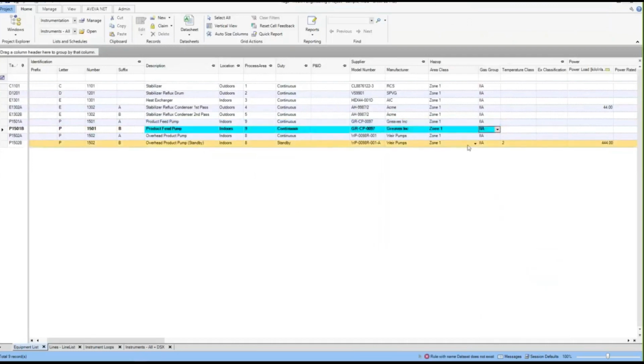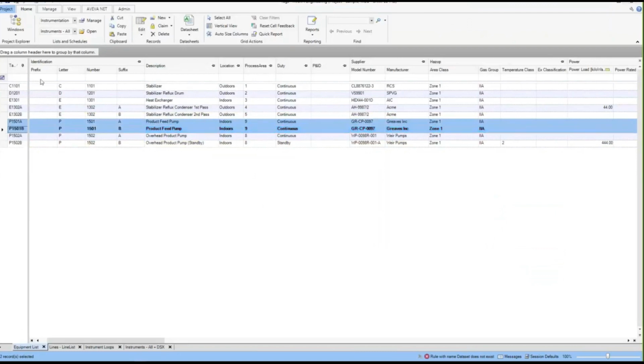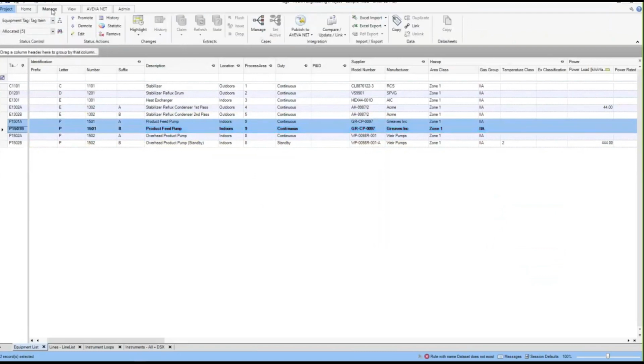The nice thing here is that we can link the two objects. In this particular case, I haven't linked them, but if I wanted to, there would be specific attributes on these two objects that are linked. If they're both main pumps, or a main pump and a standby, and you enter the design or engineering conditions, pressure, temperature, etc., that are common between the two pumps, then every time you modify the pressure, temperature, or other linked attributes, it will be updated on the standby pump.